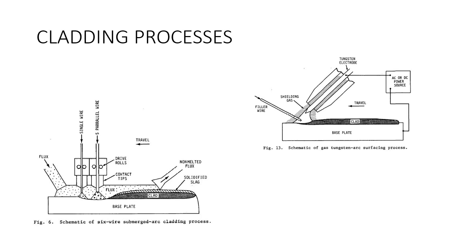I used to work for an outfit here in Houston, and we do a lot of cladding, putting nickel alloys and stainless steel type alloys on the inside of valves. We'd build up this clad material and then send it off to a machine shop, and then they'd machine it down and make everything happy.